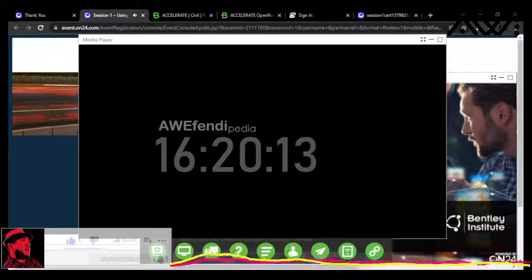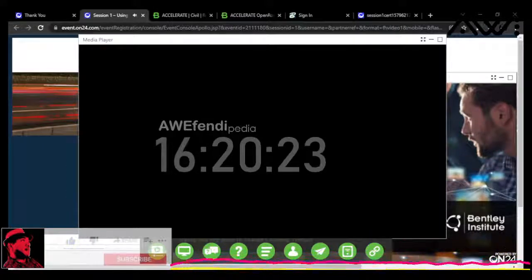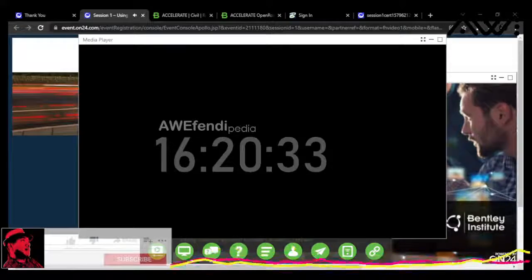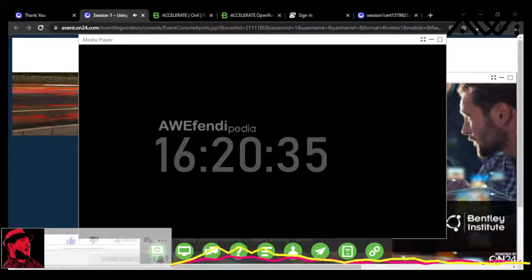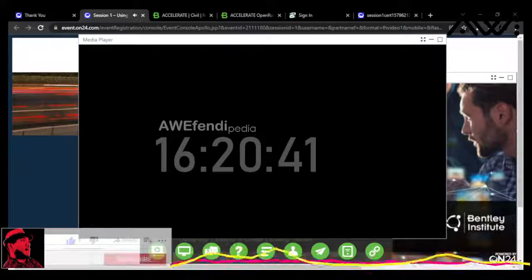I'm going to hit the add button, and I'm going to hit join point. And the point number that I want to join, I'm just going to key in 5137. I'm going to tab out to accept that value. Once I've tabbed out, I'm going to hit accept. And what that does, adding that control code to my point there, tells it to connect up the line between, whatever you're doing, to the point that I specified, which was 5137.